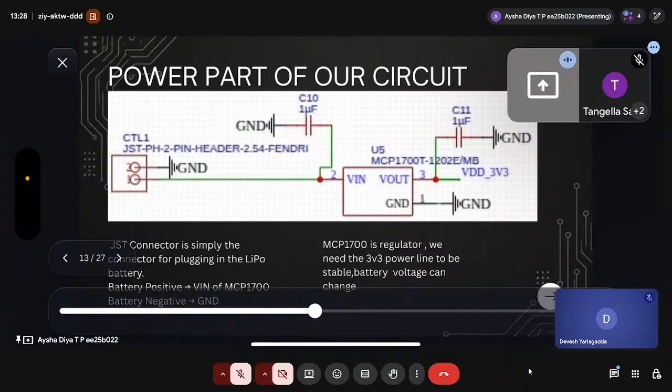So what is the purpose of this MCP1700? The battery won't be providing a correct voltage, it can fluctuate, right? But our circuit actually needs a correct 3.3 volts. To ensure that, we will be using a voltage regulator. This MCP1700 will take in the voltage from the battery, and it will always output a constant voltage. So to avoid those fluctuations, we are using an MCP1700 power regulator.